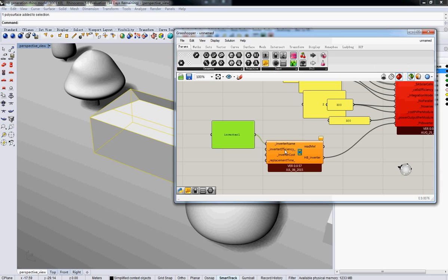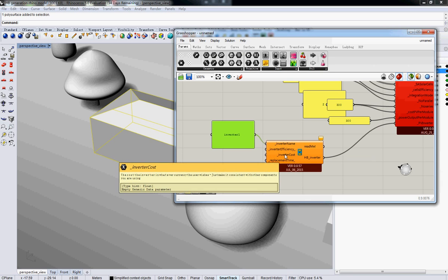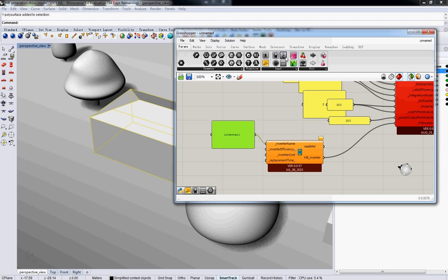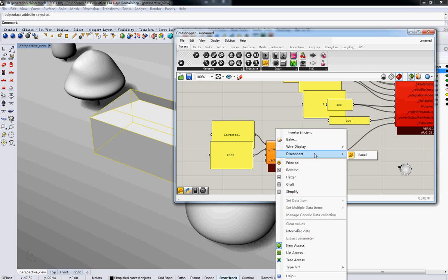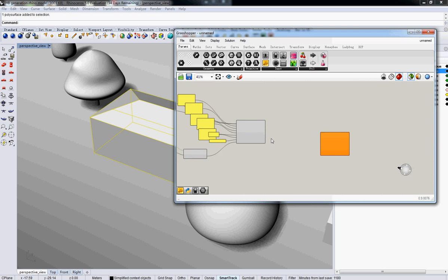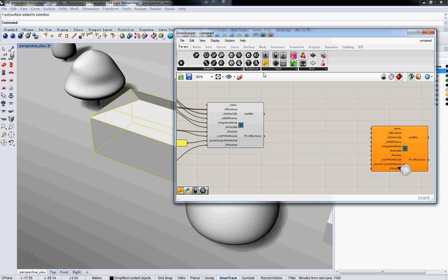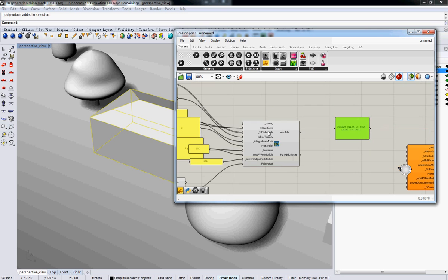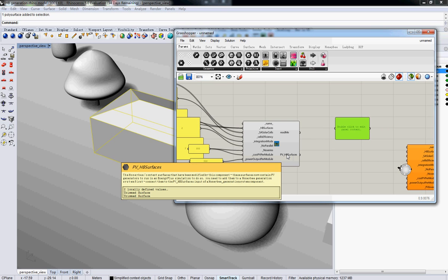Okay, there we go. The inverter efficiency, 90% is the default. The inverter cost, let's say it's $2,000. Okay, $2,000. That's inverter cost. The replacement time, so how often do these inverters need to be replaced? Let's just say once every 5 years. Okay, so now we've got 2 Honeybee surfaces with 2 Honeybee PV generators attached to them.